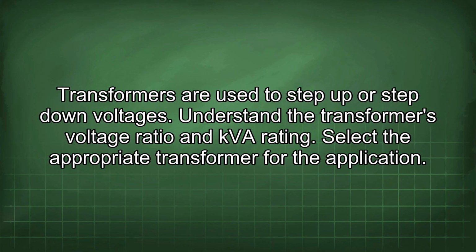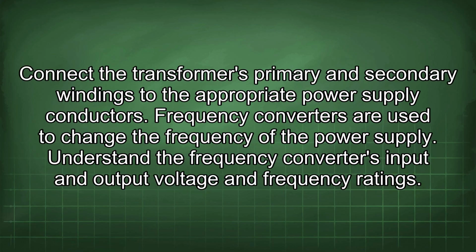Transformers are used to step up or step down voltages. Understand the transformer's voltage ratio and kVA rating. Select the appropriate transformer for the application. Connect the transformer's primary and secondary windings to the appropriate power supply conductors.